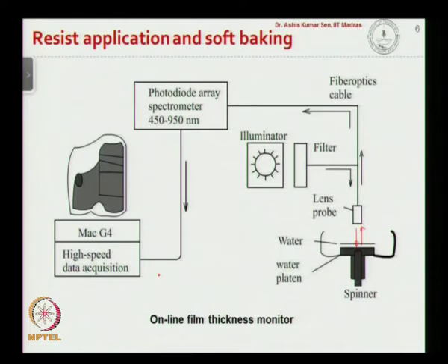By comparing the intensity of the incident light and the reflected light, with suitable correlations, we can predict the thickness of the photoresist layer.